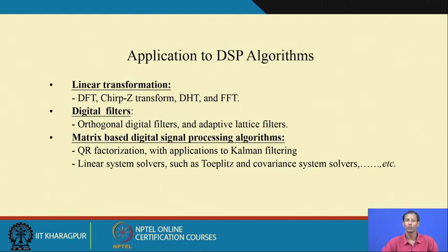For this purpose also we use CORDIC. We have noticed plenty of use of CORDIC for deriving the hardware architecture of functions like QR factorization, FFT, DHT, or DFT. This application area itself shows that CORDIC is used for various applications, mainly in DSP algorithms. It is not specific to DSP only; for wireless communication also we mostly use CORDIC.